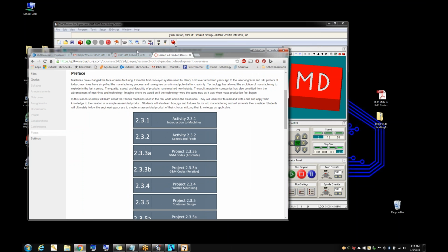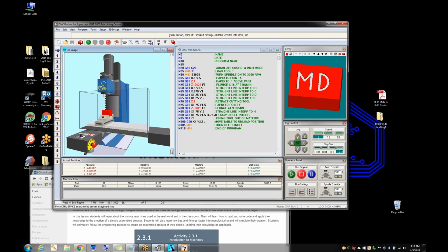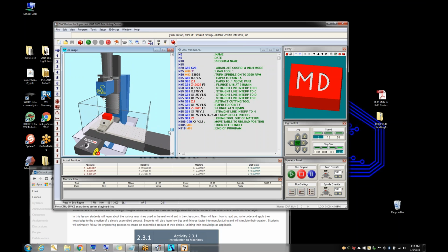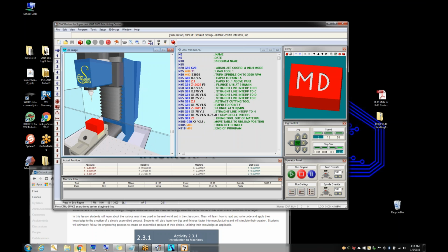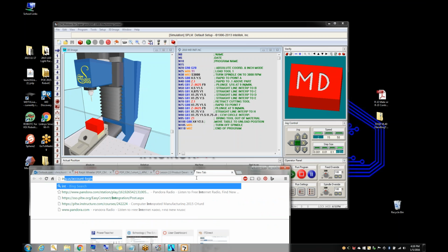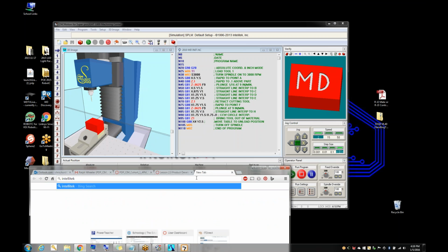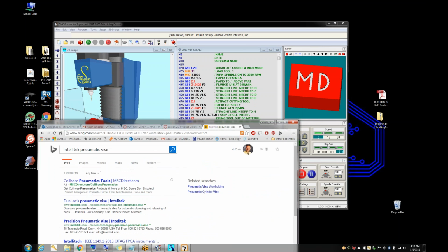Okay. There's multiple problems with the air vises. One of the biggest ones is the air vises are really set up for one specific size. So if you're going to do a 3-inch by 3-inch whatever, you set the vise up for that. Because every time the vise comes in, when it's a single acting vise, it's basically coming in at an angle and supposed to squish it into the corner. Well, if your parts aren't exactly the same size every time, then you're going to come in contact with one face instead of both faces, and you're right, you're not going to hold on to it. It's going to constantly keep letting go, especially if you're not really holding on to enough of it, 3/4 of an inch or so.